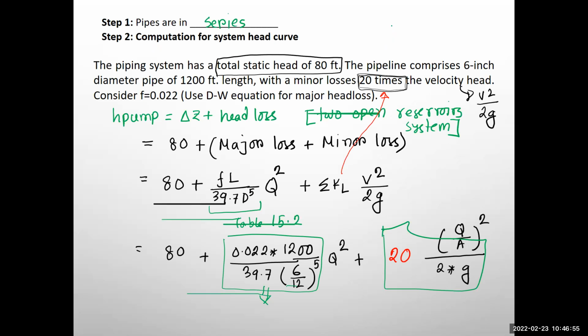So it will be, yeah, but you have two different pumps. Okay. So this system is actually for the pipe, not for the pump. So you will use the pipe diameter, which should be 3, right? Pump is for the pump characteristics curve. The pipe system curve is only for the pipe. That should be the A.